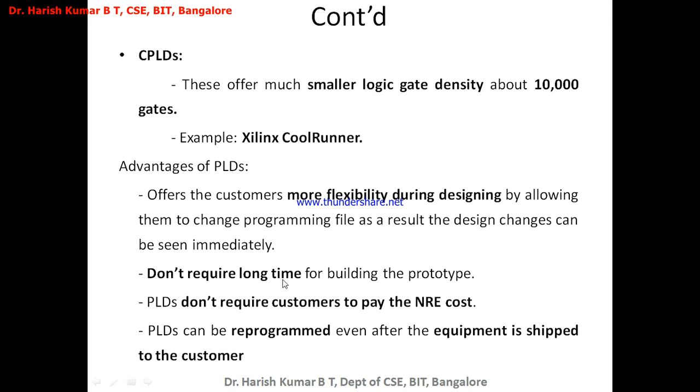And they don't require a long time for building the prototype. What is a prototype? A prototype is basically an initial model or the basic model. Using PLDs, you don't require much time to build an initial prototype or initial working model. So in very little time you can build the prototype. And they don't require the customer to pay the NRE cost, that is the non-recurring engineering cost.